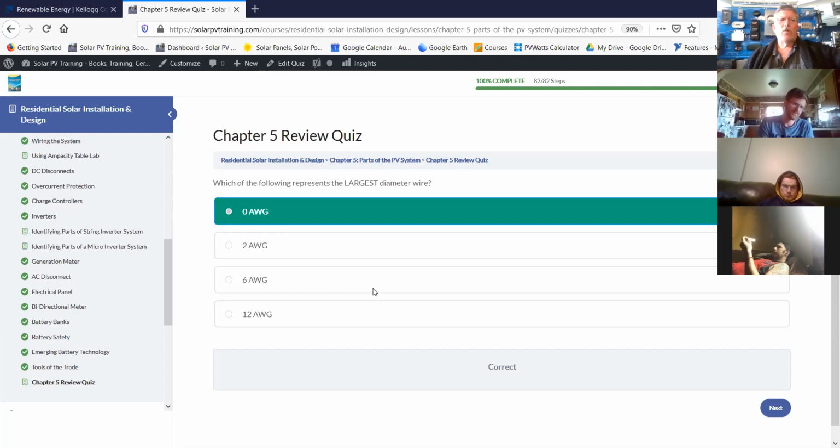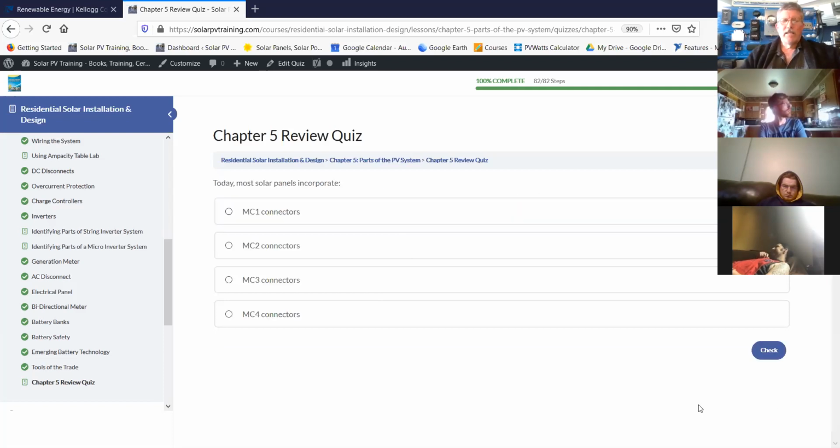You can get bigger wire than 4/0, but then they start usually referring to it in square millimeters. There are different ways of referring to it. The rest of the world, other than America, typically refers to this as square millimeters. So it makes a lot more sense. But yeah, America is always a little bit weird as far as measurements. Everything. Yeah, everything, right? Yep.